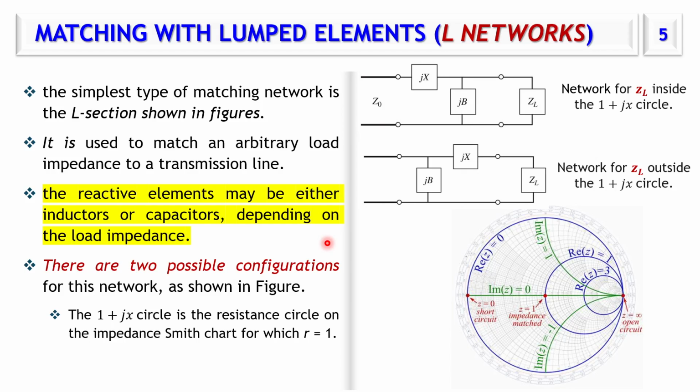Of course, an analytical solution for the matching network problem exists, but again, the Smith chart gives us some sort of visualization for this. The idea of using the Smith chart is to show the benefit and value, and it can also arrange your thoughts in a methodological way. So this L network has two different configurations: either series and then shunt, or shunt followed by series.